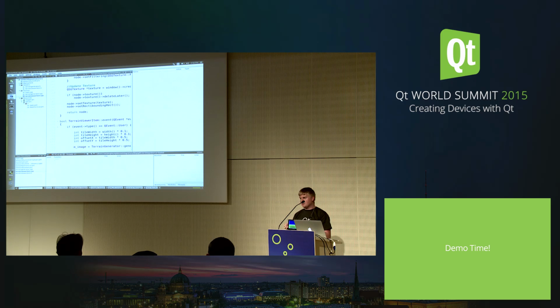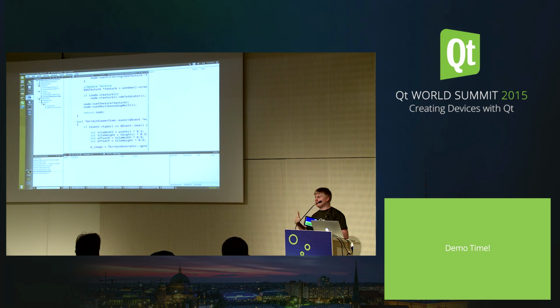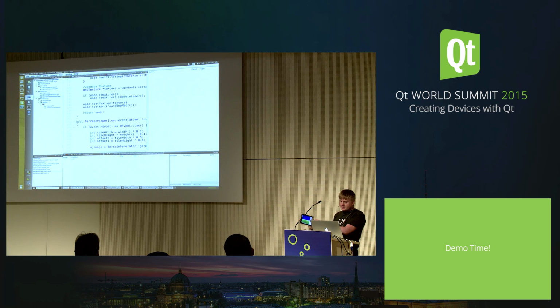But we're also starting the QML debugger. And the QML debugger is a different context there. It's JavaScript and the declarative QML or QtQuick language. So that's going to take a little bit of time to get started, it seems. And yeah, there it is. So now you can actually see in the locals view, we're not actually stopped, but we have access to the locals view. And this is actually the QML property hierarchy in real time.